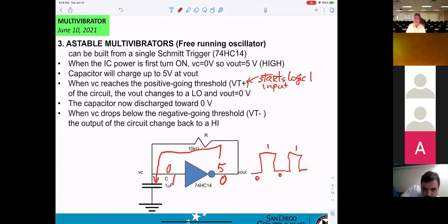And you understand for TTL logic, logic 1 will be 2 volt up to 5.5 volt. Logic 0 will be 0 to 0.8 volt. But this is a special IC. Only when the input gets up to VT plus will it be considered logic 1, so anything 2 volts or higher.